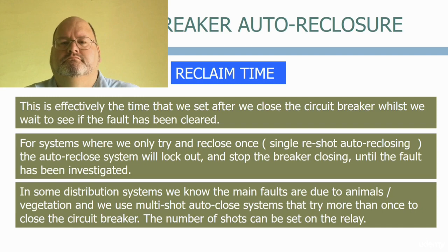When we are assessing the dead timers and reclaim timers, we are balancing the needs of the customers and the network and the integrity of the equipment. The customers obviously want a minimal outage time as it disrupts their operations. The electrical utilities are also incentivized to reduce the duration and frequency of any outages, as very often they are financially penalized every time a customer is disconnected.